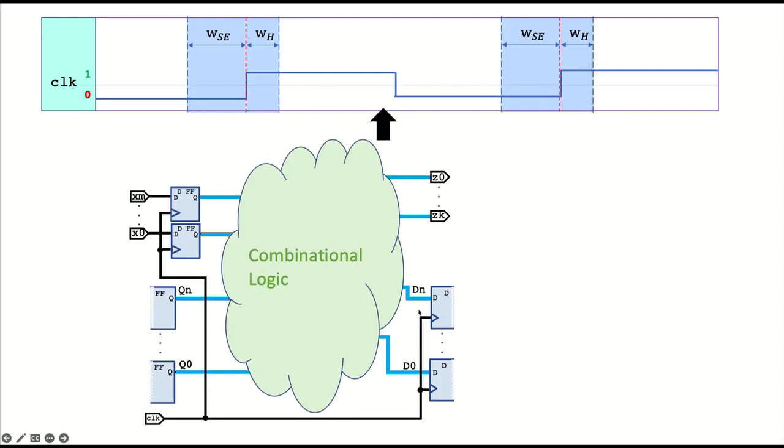All right, so now they've arrived, and now we're getting to the next clock edge. Okay, so now they cannot change again. Now they have to stay steady. And that's okay if this combinational logic has all settled, because the inputs aren't going to change. They need a clock edge in order to change, and we are not yet at the clock edge.